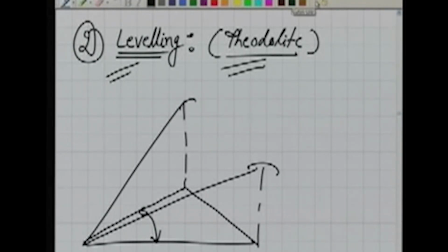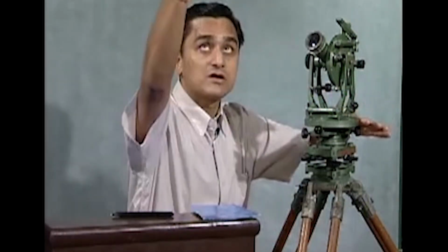So if there are 2 objects here, for this theodolite, one here, the theodolite may bisect like this and bisect like this. We are interested in the corresponding angle at the horizontal plane, the projected angle on the horizontal plane. So our measurement, or the graduated ring, has to be horizontal for this purpose. Now how to ensure it?